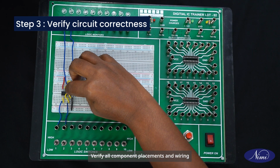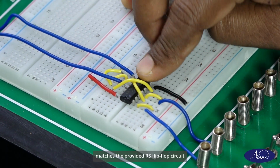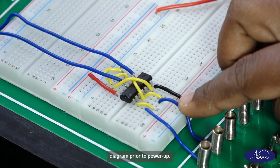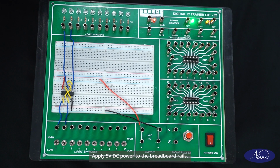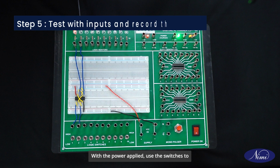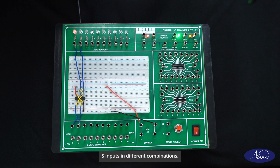Verify all the component placements and wiring matches the provided RS flip-flop circuit diagram prior to the power-up. Apply 5V DC power to the breadboard rails. With the power applied, use the switches to apply high and low logic levels to the R and S inputs in different combinations. Observe corresponding latch state changes to the output LEDs. This step verifies the functionality of the flip-flop under different input conditions.